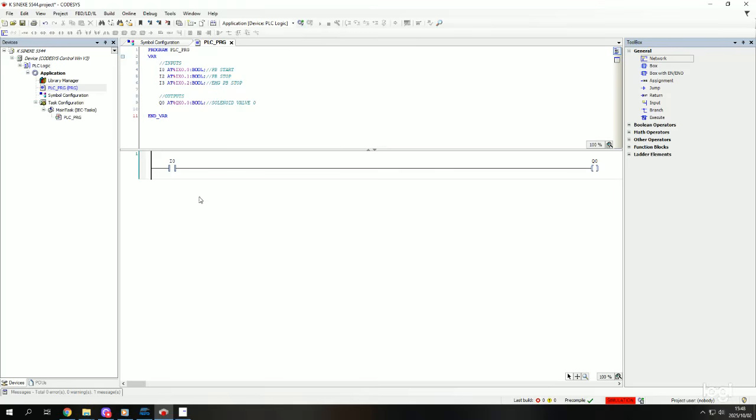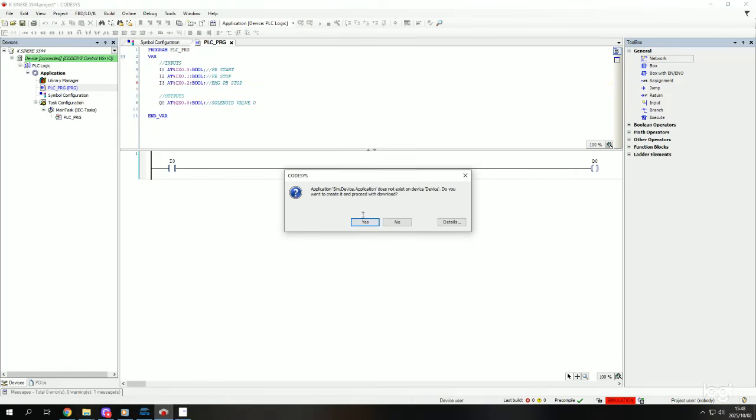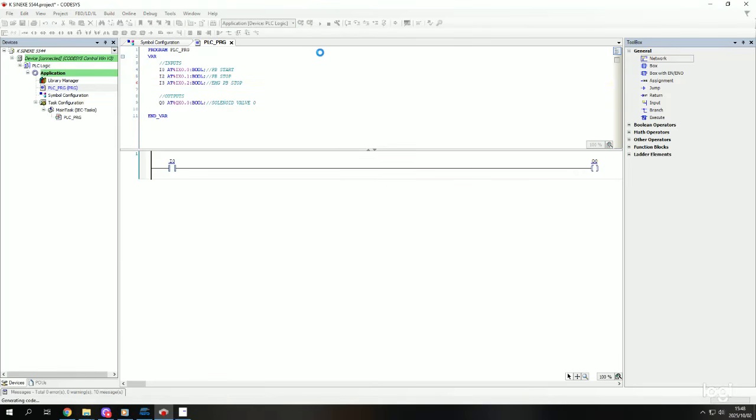Right. So this is our basic ladder logic diagram, and our FluidSim circuit should run with just this basic ladder logic diagram. However, because our PLC, we always need a stop push button and an emergency push button, even in your test, you will have to insert those 2. So just, I'm gonna click log in.